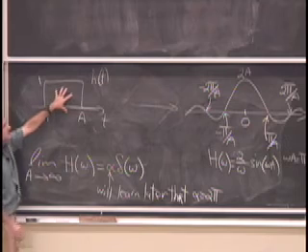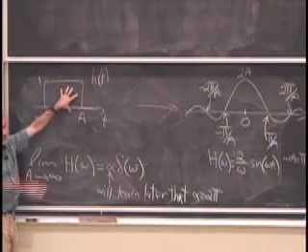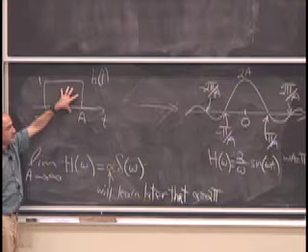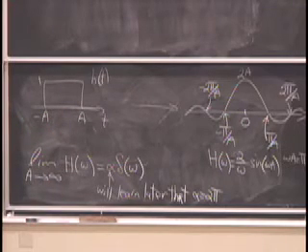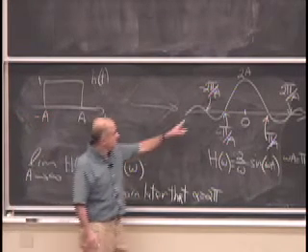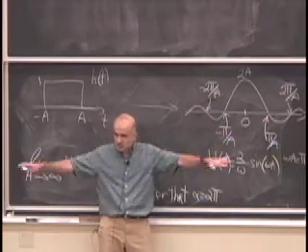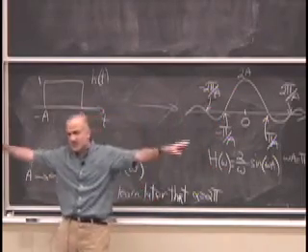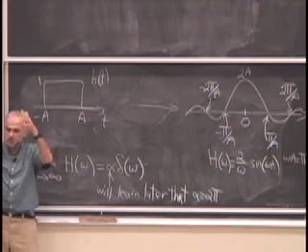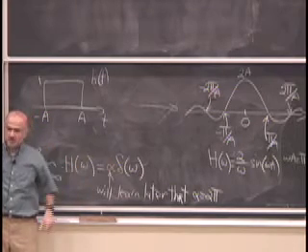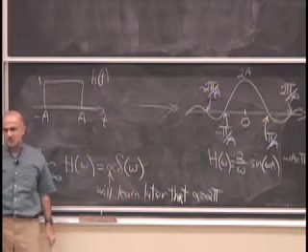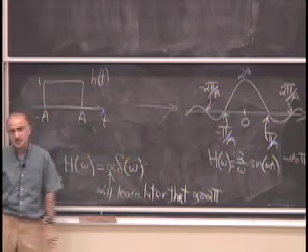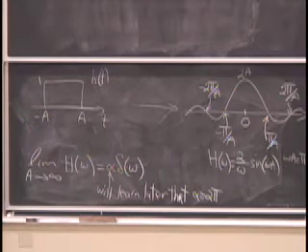But this is a perfectly valid function in the time domain with that particular integral to plug in. But this, what does it look like to you? Where's the bulk of the... It's low pass. Yeah. But it does pass all these frequencies too. It's just that it's suppressing them. Low pass doesn't mean you don't pass high frequencies. Low pass simply means you prefer the low frequencies over the higher frequencies. So the amplification that you give to the lower frequencies exceeds the amplification you give to the higher frequencies. So this still qualifies as a low pass filter.